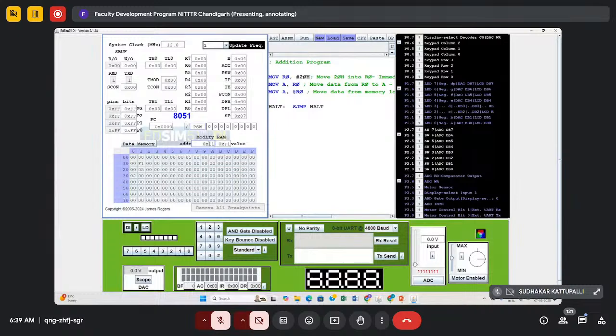In order to modify the address, you need to write the address over here, and whatever value you want to have, 1A. I want to have 1A. One second here. Okay, so now 20 is having 1A. This is a jump instruction, a short jump. I'm just ending the program; it will keep jumping over here. There are various methods to end the program. I've just written it.